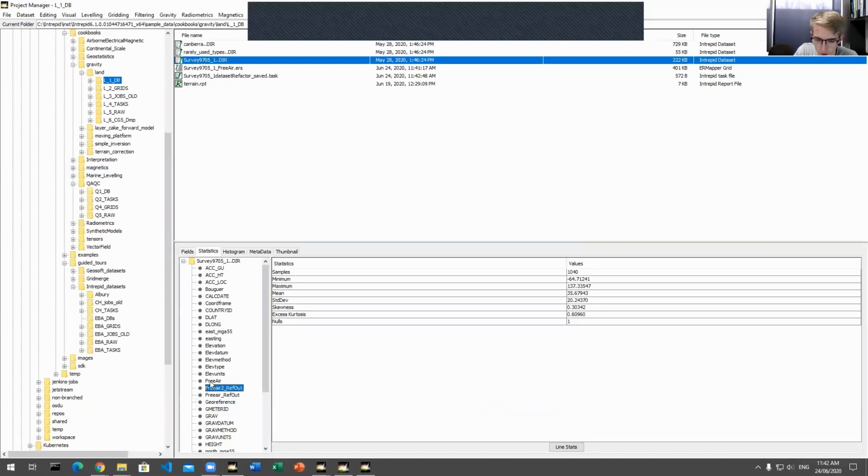One thing to note here is the difference between the original and the free air 2 is that there's one sample that gets kicked off. And that's because it doesn't actually have any northing or easting value put in. So it doesn't get loaded into the refactor workflow. So it removes an erroneous point that doesn't really make sense if it hasn't got a location.